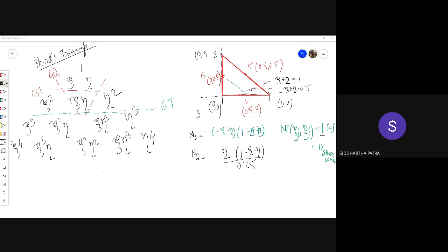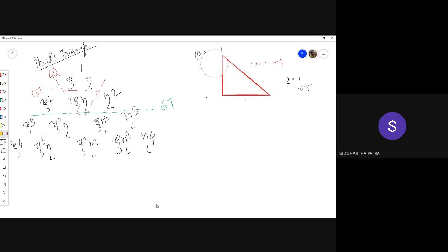So you can construct the remaining ones following the same procedure, and the rest of the procedure is very much the same. One good thing about the finite element method is that once you learn how to do the formulation for one type of element, you can do that for any other type of element. So I'll leave it over there and move to quadrilateral elements. Now, how do I make quadratic quadrilateral elements?